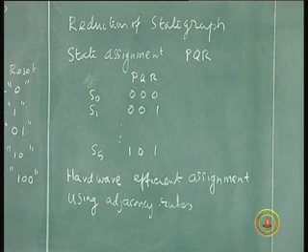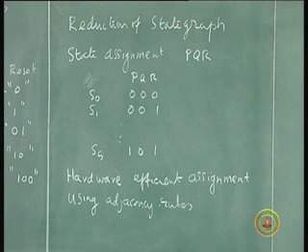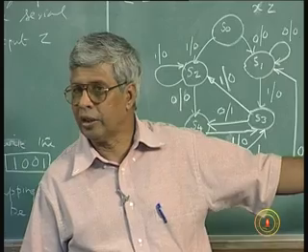So to that extent it will also impact the hardware, but a more significant reduction is possible if you can even reduce the number of flip flops. The same argument I can hold here. If you have a state assignment such that the transition always happens from one state to the next state which differs in only one variable, the switching activity or the transition is minimum, and that is also efficient. Again I am going to skip this part.